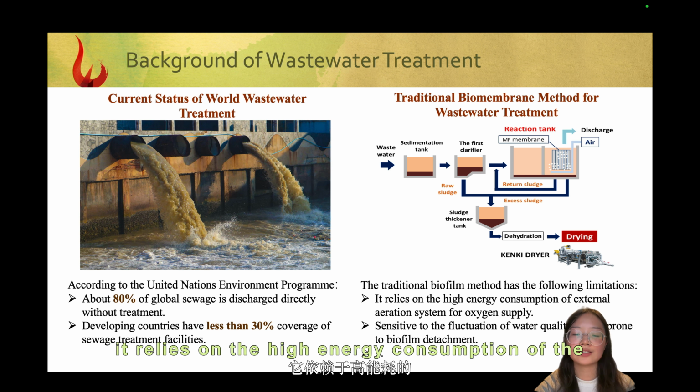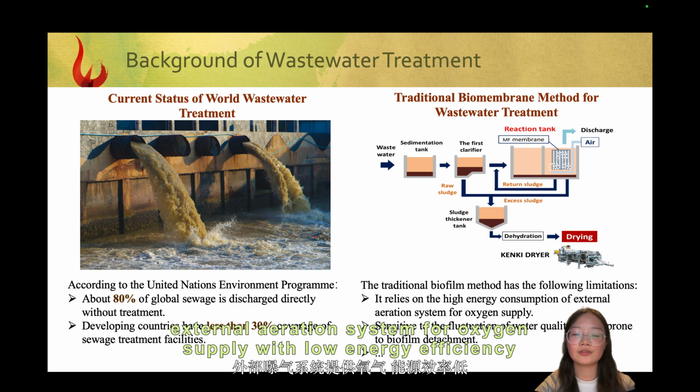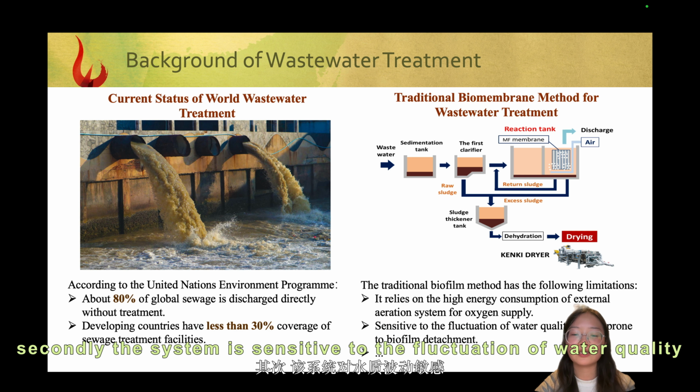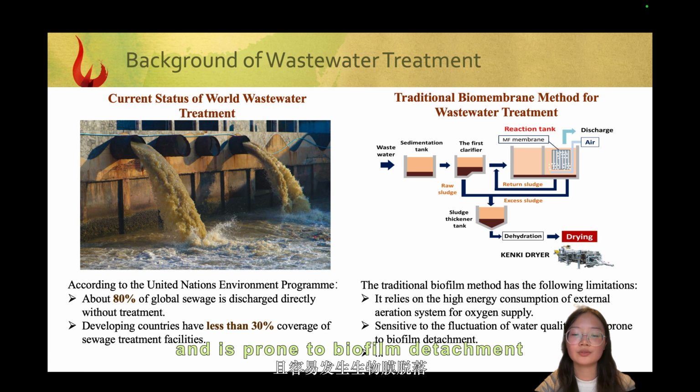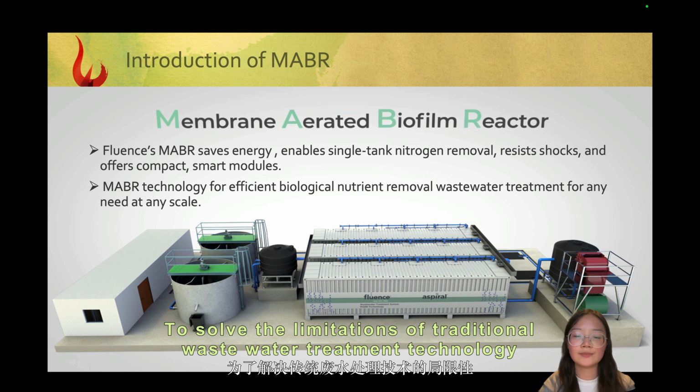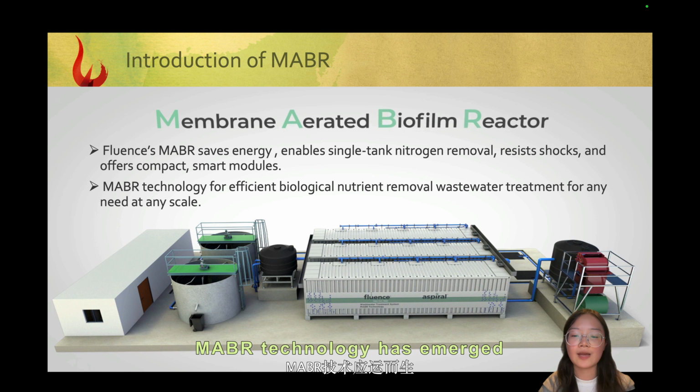Firstly, it relies on the high energy consumption of the external aeration system for oxygen supply, with low energy efficiency. Secondly, the system is sensitive to the fluctuation of water quality and is prone to biofilm detachment. To solve the limitations of traditional wastewater treatment technology, MABR technology has emerged.